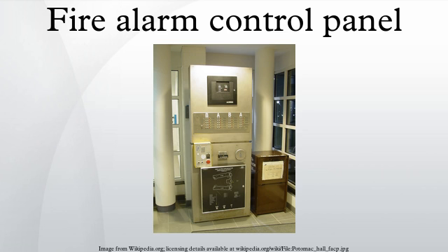Even larger systems and demands for finer diagnostic and location detail led to the introduction of addressable fire alarm systems, with each addressable device providing specific information about its state while sharing a common communication circuit. Annunciation and location strategies for the most part remain relatively unchanged.